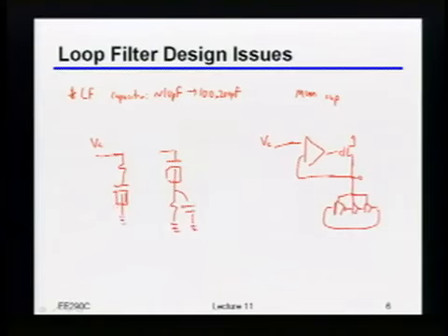Okay, now, there is one unfortunate thing, which is kind of changing as we speak, or has, but will probably come back. Some of the more advanced technologies, if you take a transistor and just put a voltage on the gate, you'll find that magically current flows from the gate either into the source or the drain or the body, because, again, those quantum mechanics guys just came and bit us, and we get tunneling current, okay?